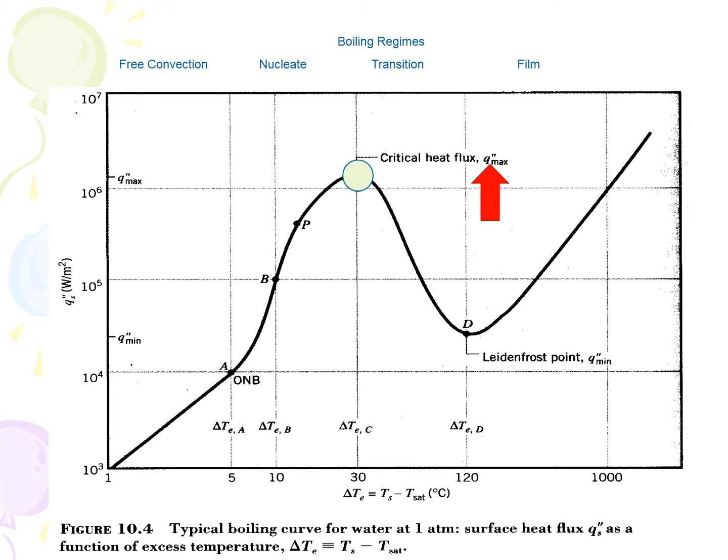From the onset of boiling to the critical heat flux, the boiling regime is nucleate boiling. This is as you often have imperfect sites on the hot surface that heat up more and act as nuclei for the production of vapor bubbles. Here convection heat transfer is increased due to advection caused by rising bubbles of steam. As you approach the critical heat flux, however, more and more of the hot surface becomes covered in vapor. Heat transfer from a surface to a vapor is slower due to the low conductivity of the vapor. This then more and more cancels the positive advection effect of rising vapor, causing the maximum heat flux to be reached.